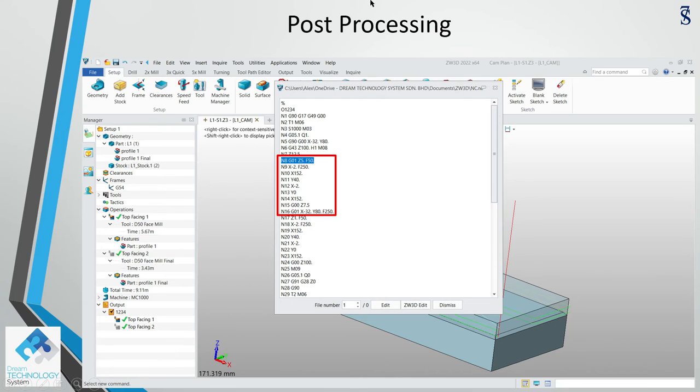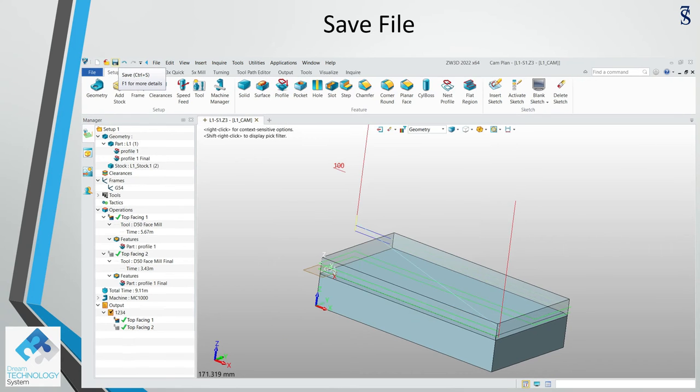Now you can see that there's extra from previously. Z is 1, then we do a roughing cut, which is the depth balance 1 mm for the final. Now we have a Z5, so we take out 5 mm on top, and then after that 4 mm for the bottom second pass, then balance 1 mm for the final cut. After that, we can save this file, and then we can complete the whole process of changing the raw material from 5 mm to 10 mm.